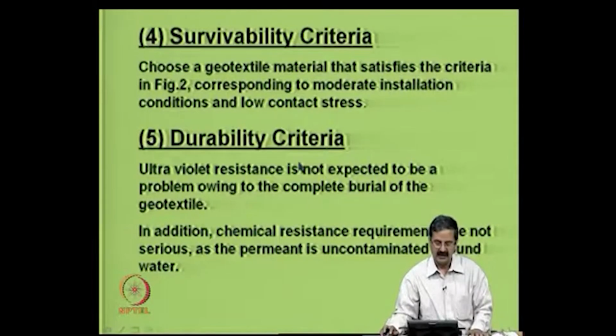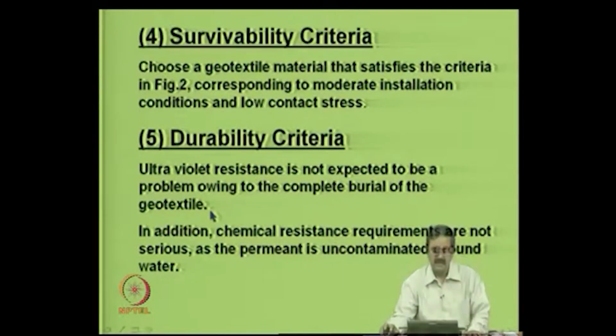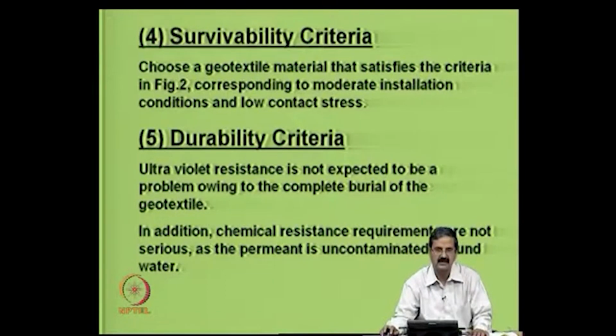Durability is another issue that one needs to see. Since we are placing this geotextile beneath the gravel cover, you are burying it, so exposure to sunlight or ultraviolet resistance is not an issue at all. Chemical requirements are also sometimes important, but fortunately in this case you are dealing with only water, so there is no problem. But in some cases where chemical substances are there and there is some interaction, one should be careful and take an appropriate material. These are all polymeric materials. If there are chemical reactions, one should see that they will not impede the purpose of this material.